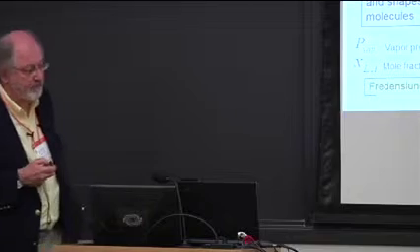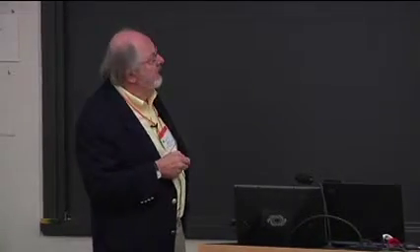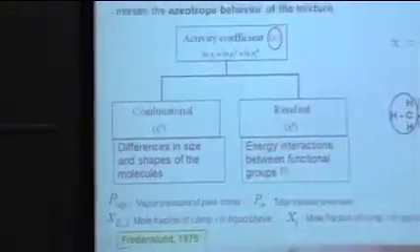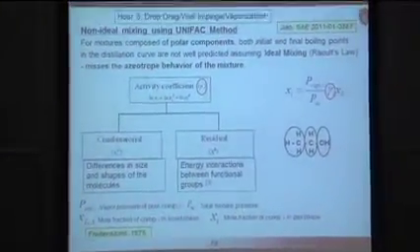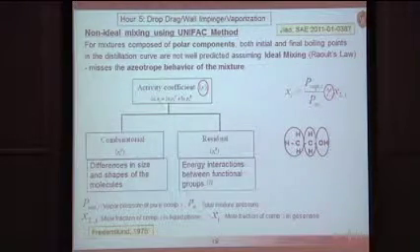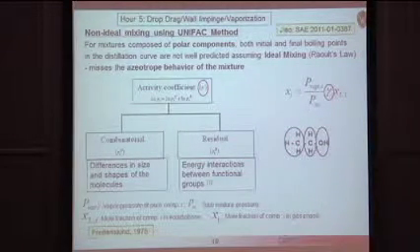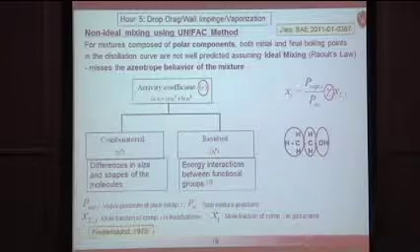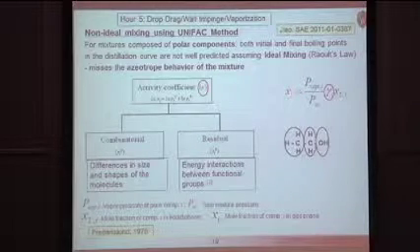Okay, so this brings me to the other part of these vaporization models that's pretty important. And that has to do with the fact that most fuels are non-ideal. Right? So we have a situation where the molecules can actually interact with each other, and this affects the vaporization process. So the use of Raoult's law, which essentially says that, as I just said, the mole fraction in the vapor phase,